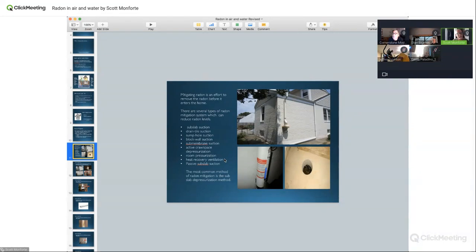Well, if you damage the pipe, if somebody hangs a picture, if somebody drills through the wall and puts a hole in that pipe, if the fan is in the basement, it's going to push the air out through that hole and you're going to have radon within your walls. If there's a weak spot, it's where the rubber fernco cones are on the fan.